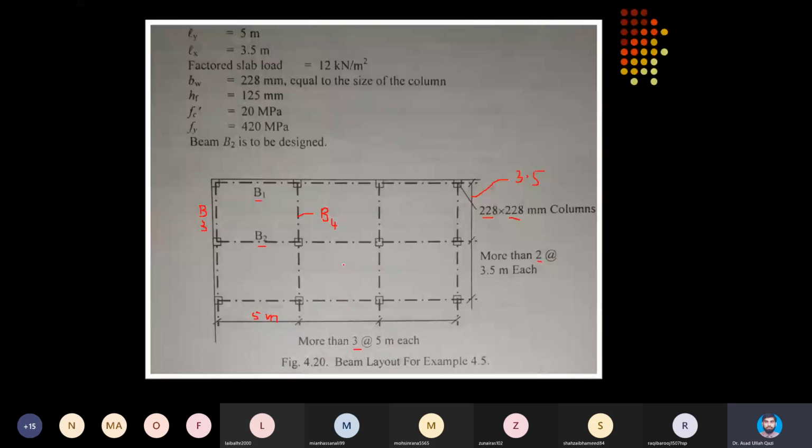If slab system is square, then along x and y direction almost the same edge beams and interior beams design will become valid, because load distribution will remain the same in X and Y direction if panels are square, because triangular loads will be transferred to the beams.